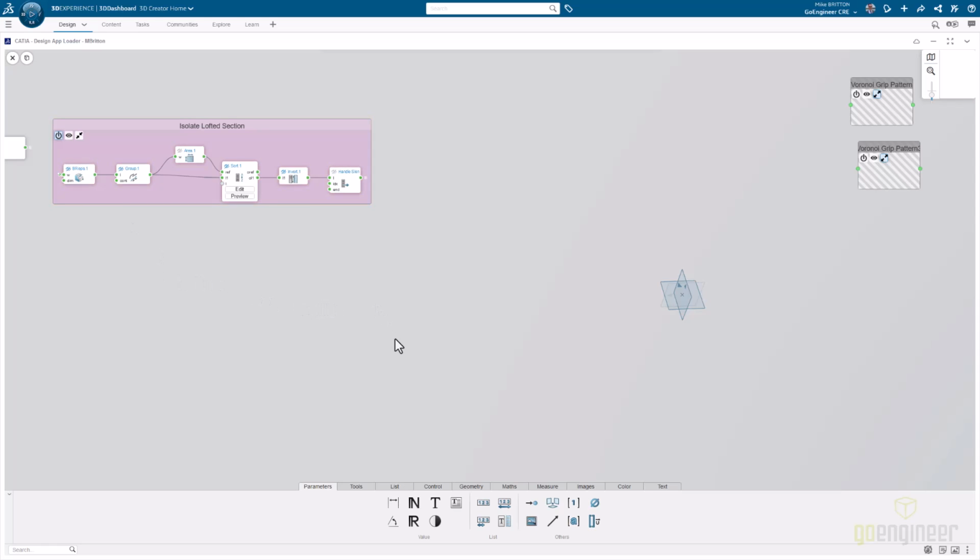The first thing that I'm going to do, and I'm just going to search for commands like I do in SOLIDWORKS, is I am going to get the triangulate operator. So we have this guy here, and as I click on this, I can hit my little question mark, and we can see the help menu pops up. It's super handy. I use it almost every single time. It is asking for a surface to triangulate and the length of sides of the triangle.